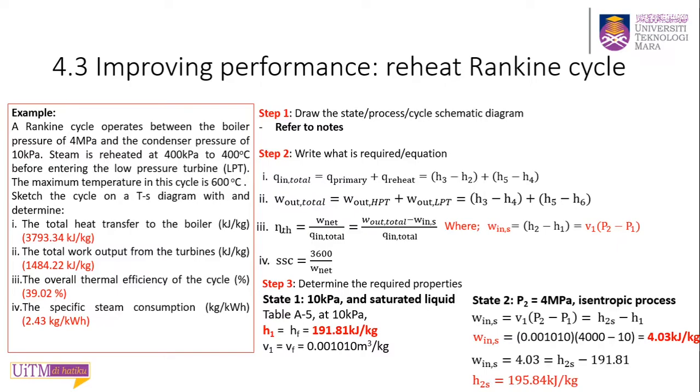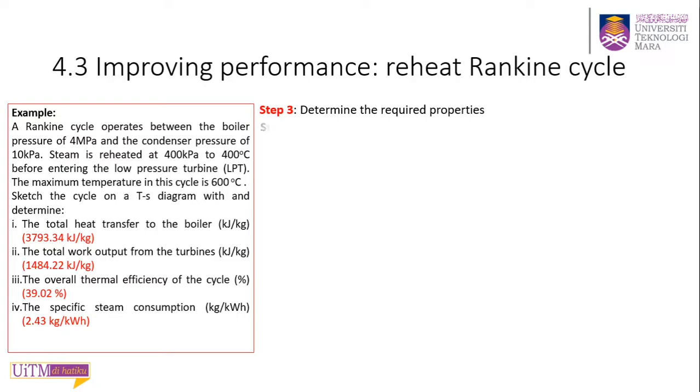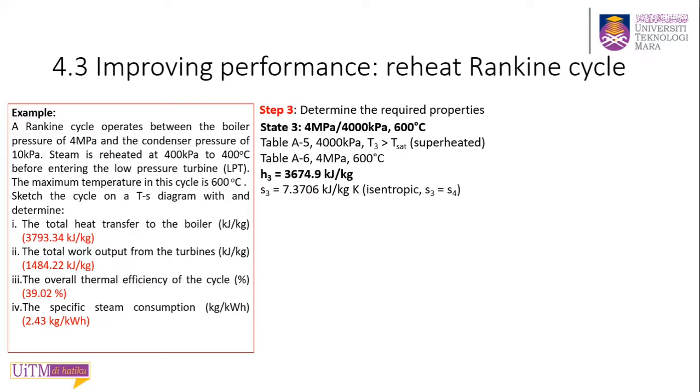At state 3, using the given properties, remember to check the phase first and then read the specific enthalpy and specific entropy here at state 3.